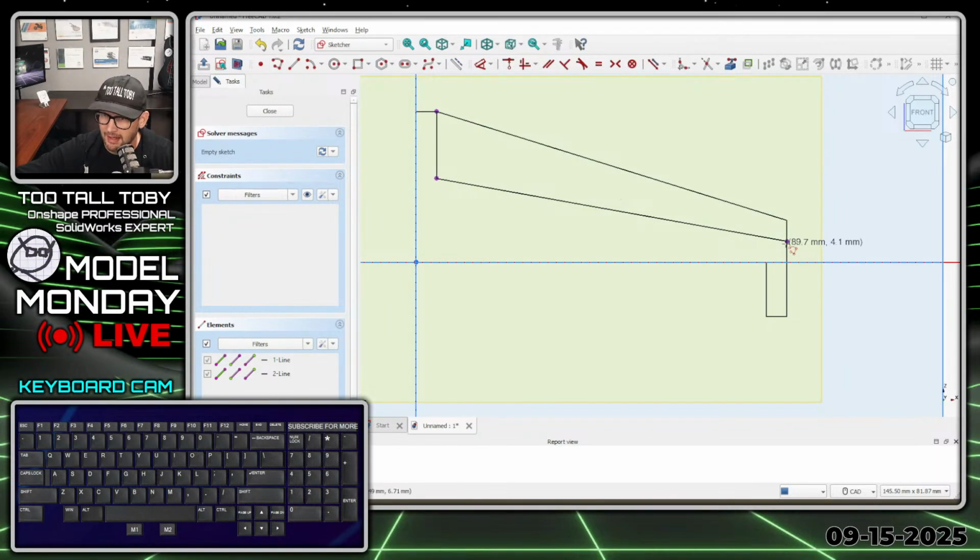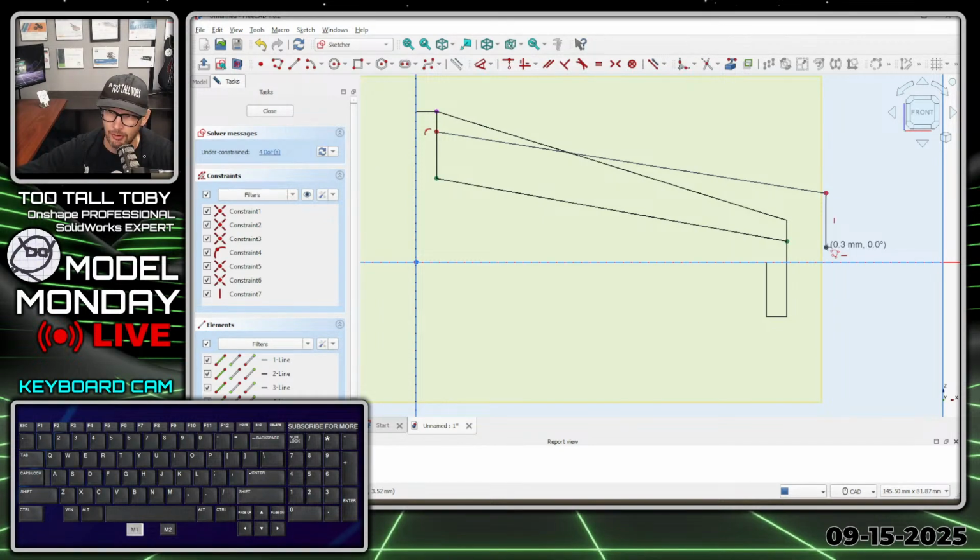Then I go to polygon, and once again, I'm going to create a line here that covers that first line. Whoops. Messed that one up. Let me just Control Z to undo that. I'll just do it again. I think that'll be a little easier. Polyline again here from here to here. Polyline that comes up to a little bit more than halfway. Don't pick up halfway. You don't want to get midpoint by accident. Polyline that comes out here a little bit above, and then make sure you get vertical there. Hit escape, and then you can hit escape again.